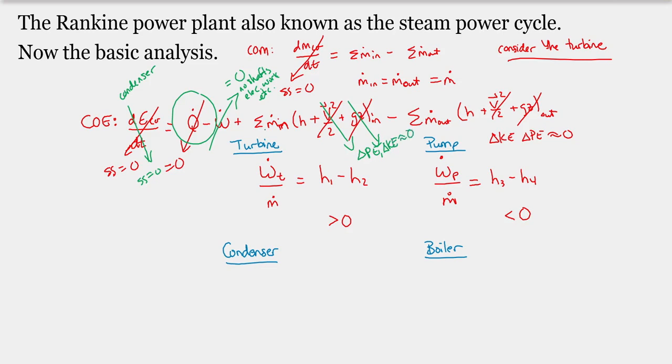And all we're left with is essentially that the heat transfer has to be balanced by the enthalpy transfer. So we have an expression that looks like this for the condenser. So Q, I'll call it condenser, which is also Q out. Again, I hope you're very flexible at understanding how to label these and which one works best for you. But condenser, out, cold, however you want to label it, this is the heat rejected from the power cycle, has to be balanced by the enthalpy at state 3 minus the enthalpy at state 2.